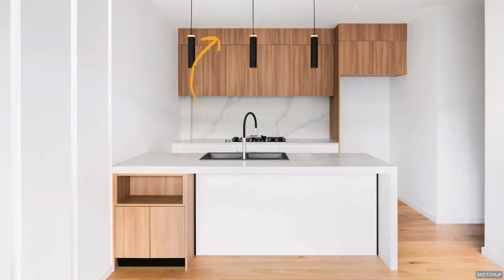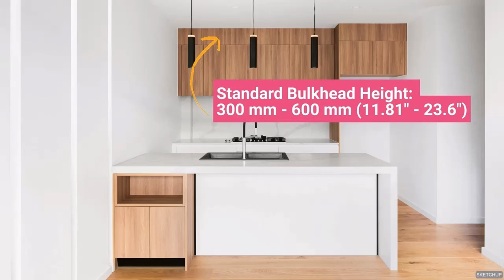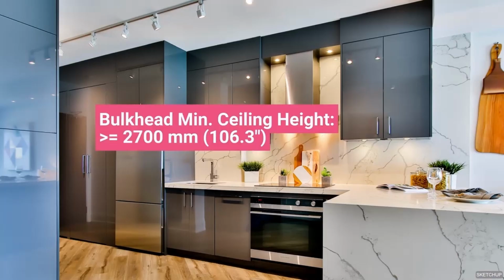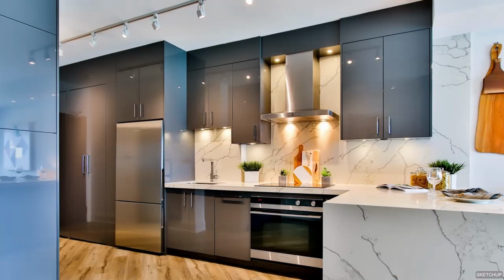Bulkheads typically measure between 300 to 600 mm in height. Only introduce bulkheads if your ceilings are 2,700 mm or higher, as bulkheads may visually reduce the ceiling height.